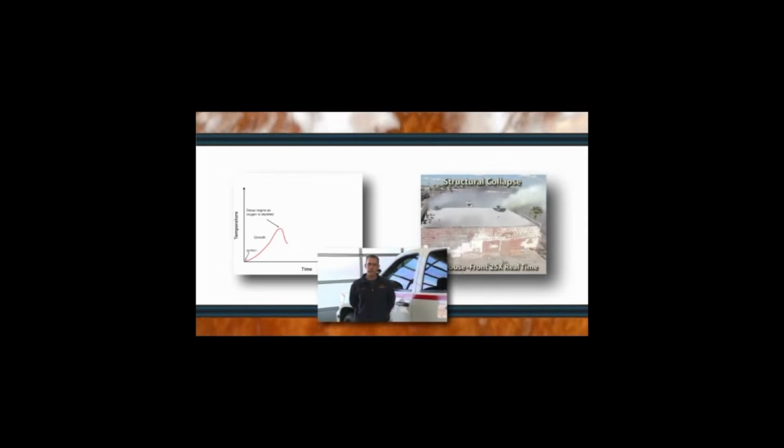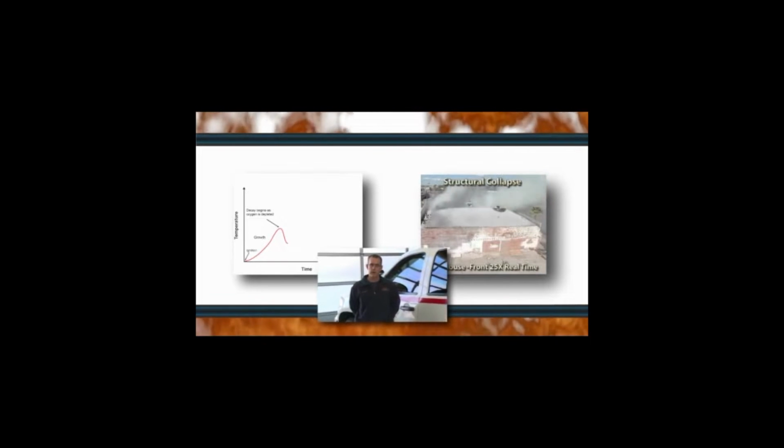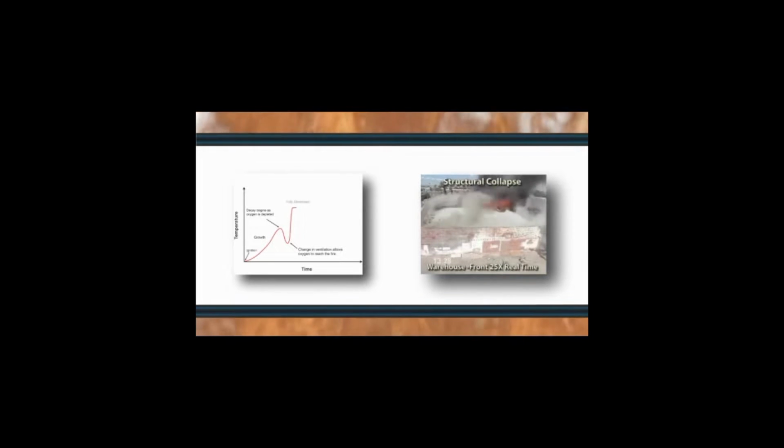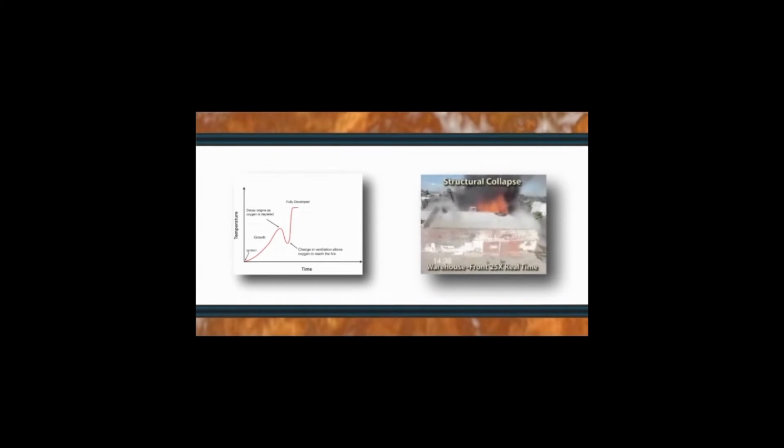Then as it becomes ventilation-limited, it actually begins to look like there's not a whole lot of fire. As the fire runs out of oxygen that it needs for combustion, it reduces the amount of heat and therefore the amount of pressure it creates. Therefore, there is less smoke being pushed out of the building. The front doors are ventilated at the 8-minute mark, and now the fire is receiving additional oxygen. And as we would expect, the fire increases again. Finally, as it gets down into the 16 to 18-minute mark, there is a catastrophic roof collapse.